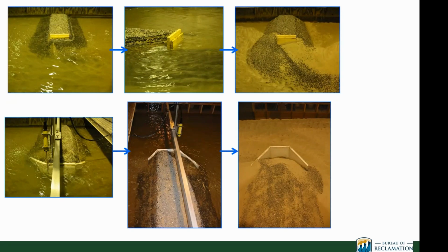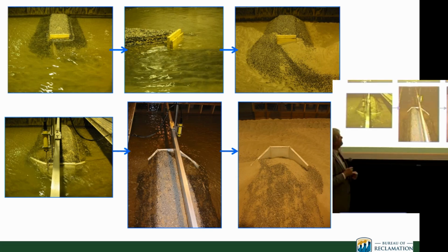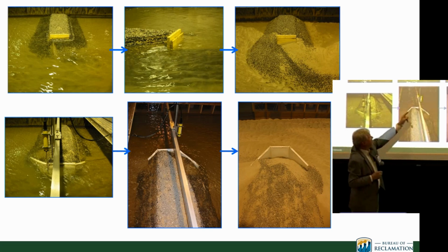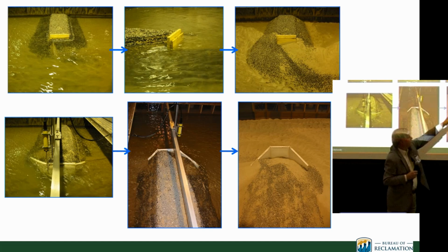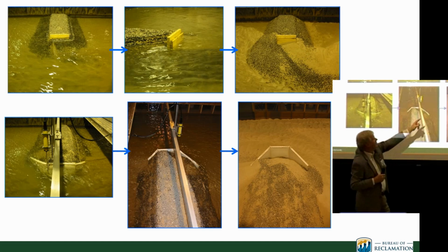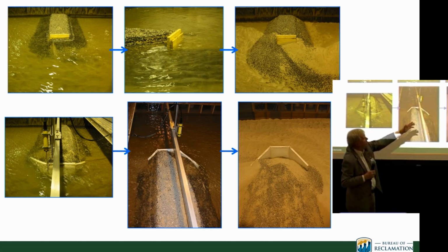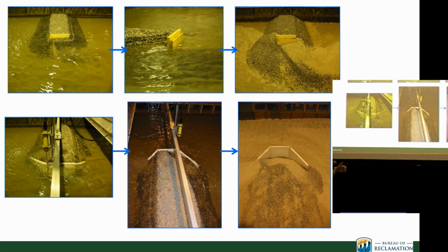So this is sequenced here, just illustrates the type of scour that can occur when the floodplain and the abutment approach are erodible. So you have flow contraction around there. It starts to eat into the embankment, the soil embankment behind the abutment column. Bridge deck is still standing. Eventually you have a failure like that. The deepest scour is out here in the vena contracta area. Here, vena contracta is more important for spill through abutments and wing wall abutments. Same thing for wing wall abutments.